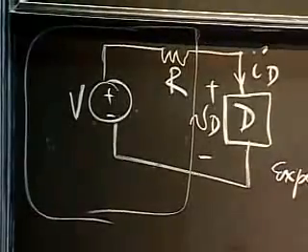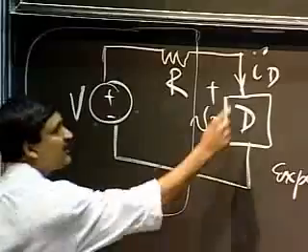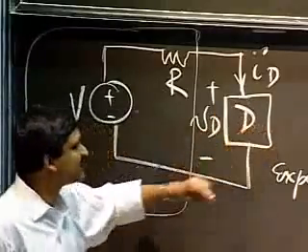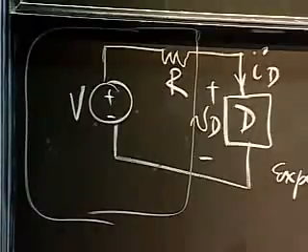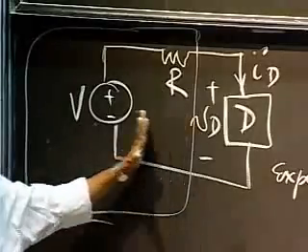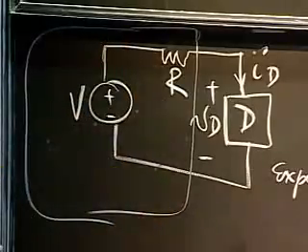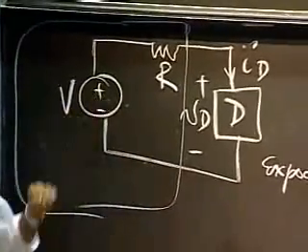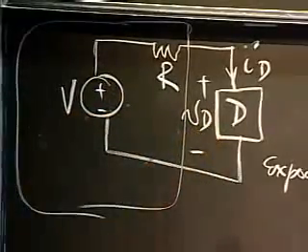So we can trick you. We can give you a complicated circuit and say, aha, tell me what the current is through this device if I apply some voltage, 3 volts, there. What you can do is say, aha, I don't care about what happens here. So I'm just going to replace the whole thing with the Thevenin equivalent. And you've done a homework now, and you can calculate Thevenin equivalents for circuits. Simply replace this and then go ahead and solve the circuit.